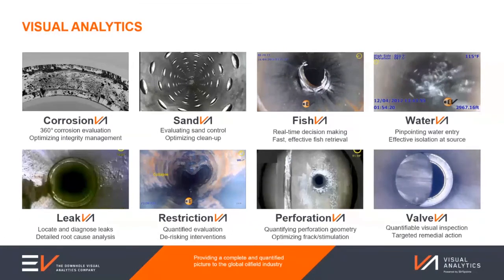The only concern that we've had when discussing this with the production logging provider is that in a lot of cases, we'll want to put a down view camera at the bottom of the string, and that is by definition a bottom-only device. But as long as you have, let's say, either an inline flow meter a little bit further up, or potentially an array flow meter behind the camera, for a lot of the cases where the video adds value, a full bore or a bottom spinner is not really going to be of great loss from the data set, and the value of the video information overcomes that. So that's one way we can work, and certainly if you're working on coil or slickline and doing memory operations, that's a really simple thing to do.